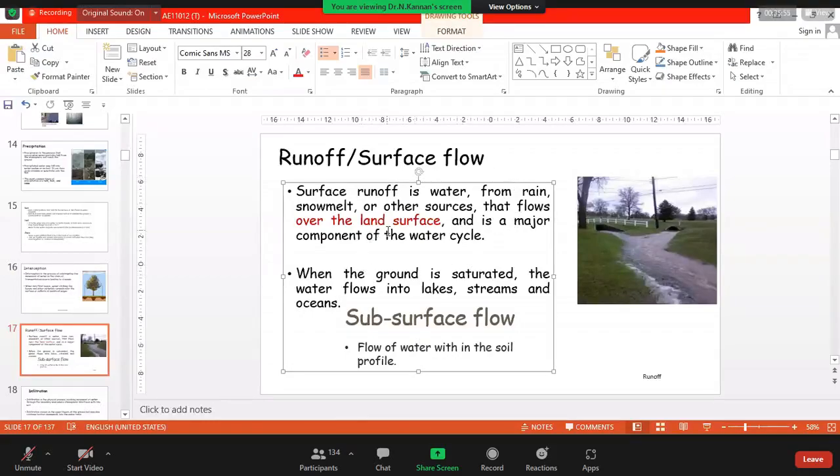Some students are asking me to explain this slide again. I'm explaining it, right? You see, it is important. I have told you this one. This is, of course, precipitation. And this one is the amount of water that is moving downward. This process is called infiltration, right? We can say this one is X, this one is Y. If Y is greater than X, then of course there's a possibility for you to have this flow which is over the soil surface.